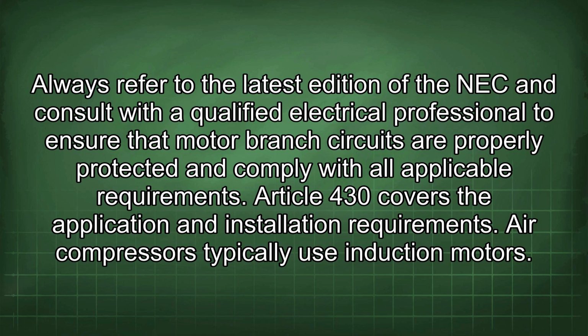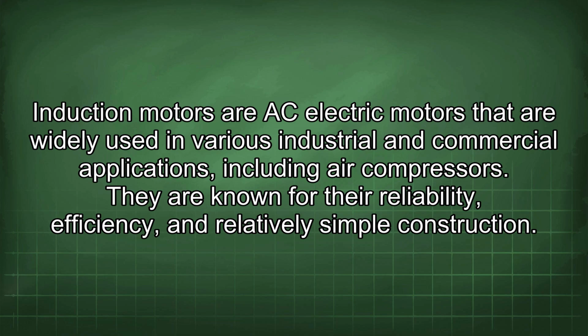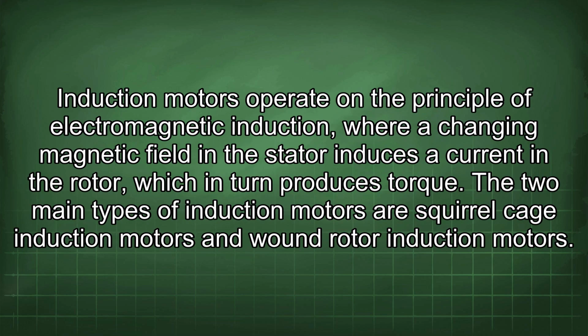Air compressors typically use induction motors. Induction motors are AC electric motors that are widely used in various industrial and commercial applications, including air compressors. They are known for their reliability, efficiency, and relatively simple construction. Induction motors operate on the principle of electromagnetic induction, where a changing magnetic field in the stator induces a current in the rotor, which in turn produces torque.